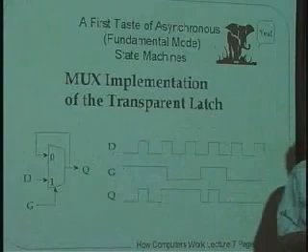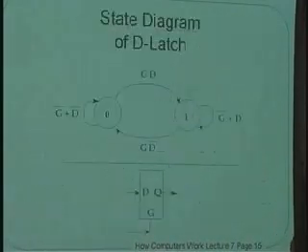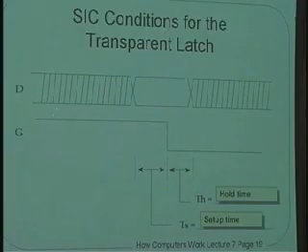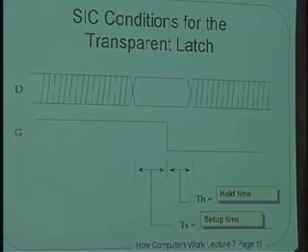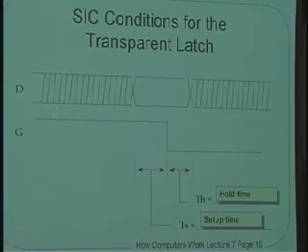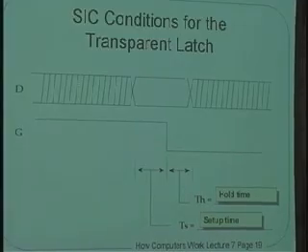And it turns out that that sort of limitation, saying only one input changes at a time, is exactly the same as the thing we talked about in the last lecture, saying that there should be a setup time and a hold time around the instant that a memory element needs to capture whether an input is a 0 or a 1.